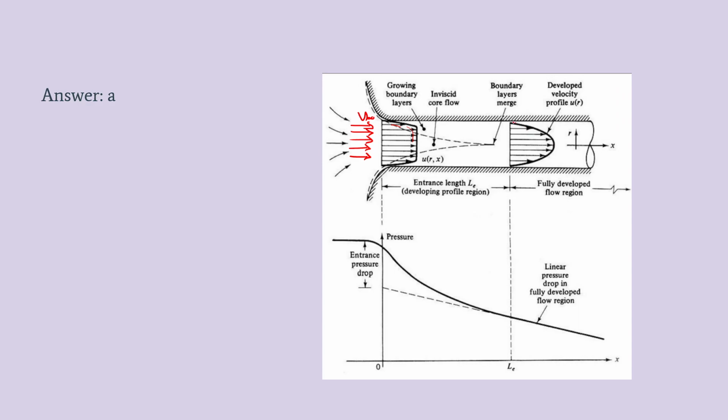We know that the parabolic profile is the velocity profile inside a circular duct. So the flow is governed by the Hagen-Poiseuille equation. Our question was for the developing region, so it was for this region. Here you can see the velocity is varying in the axial direction because the shape is something like this here, and it is changed to this one.